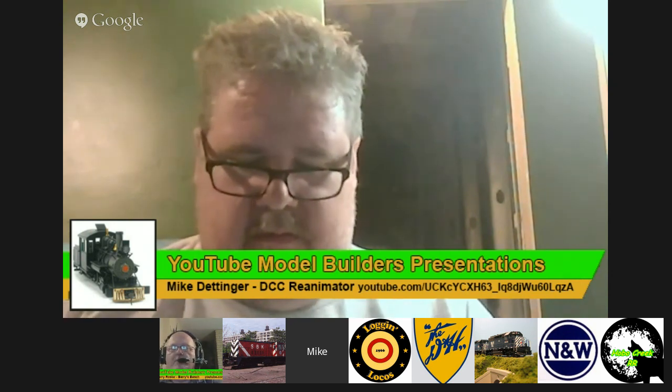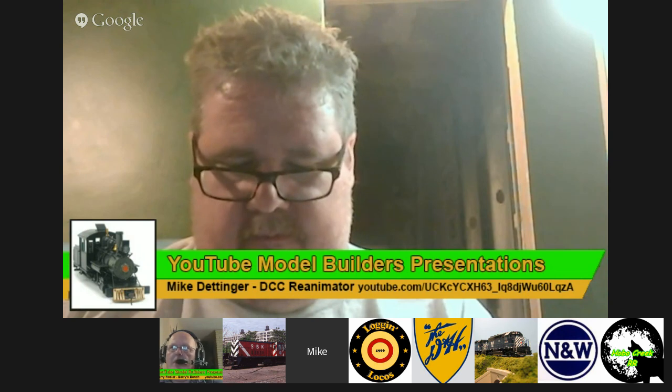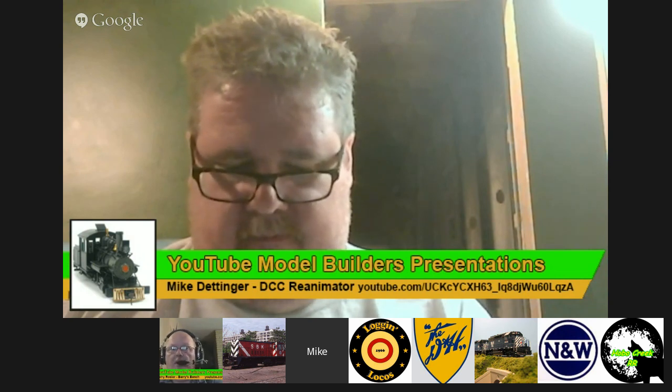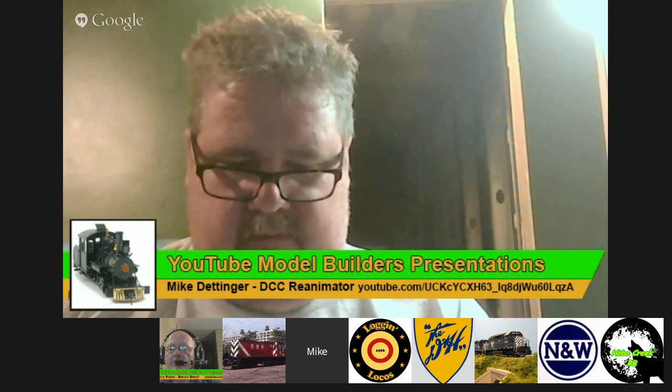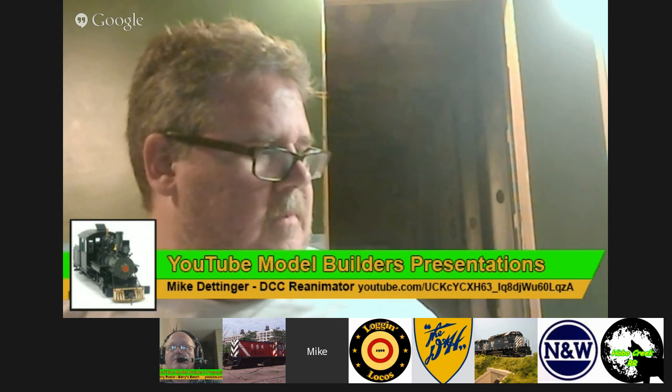Mostly, that's why he has all those PM42s under there. They're not power matchers. They're all auto reversers for his yard loop and his mainline loop and everything. 5 PM42s. Yeah, I mean some of them are for power management, but at least 3 of them I think are for auto reversing sections. Yep. And not that they're reverse loops, as in used to reverse a train. They just, because the way the main line comes back in, it formed a reversing loop.